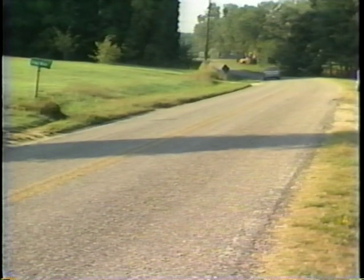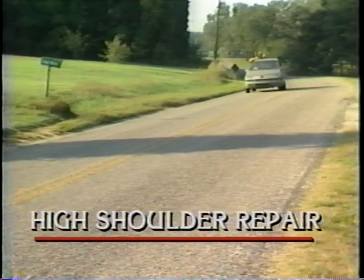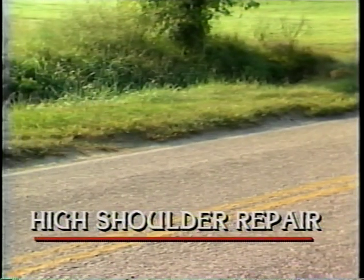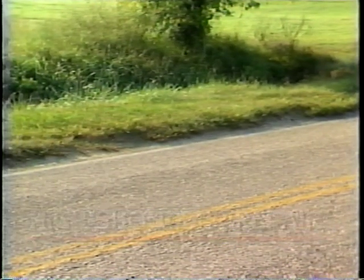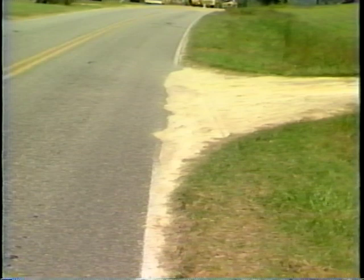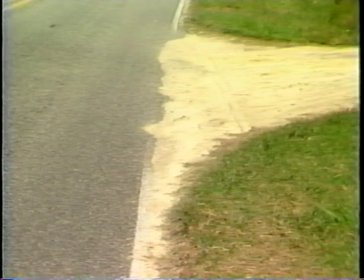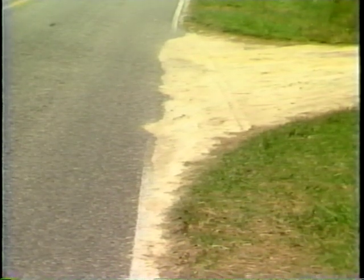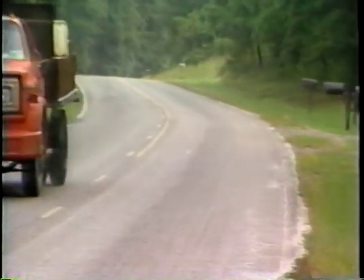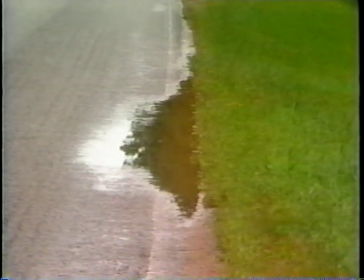The last of the shoulder maintenance operations is high shoulder repair. On this roadway, the shoulders are approximately 2 to 3 inches higher than the edge of the pavement. This condition can be created by several things. High shoulders can be caused by soil material being washed away from driveways or other intersecting roads and collecting on the adjacent shoulders. High shoulders create a problem because water will pond at the edge of the pavement. It is trapped there and not able to drain across the shoulder and into the adjacent ditches.